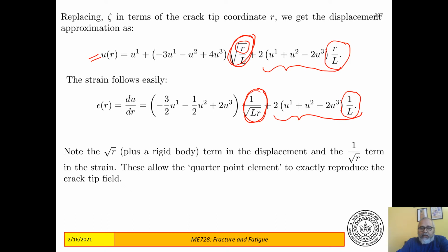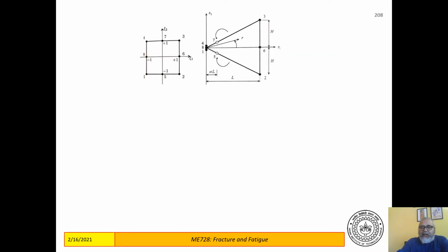That's what we have shown here. Now, this is for a 1D case, and let us see how it is for a two-dimensional element. So let's take a quadratic rectangle. This is a quadratic rectangle, and the numbering that I have used is like this: 1 is here, 2, 3, 4, and then the mid-side nodes go as 5, 6, 7, 8. If you change the numbering, the story will change. The order of the shape functions will change from what I'm going to write here.